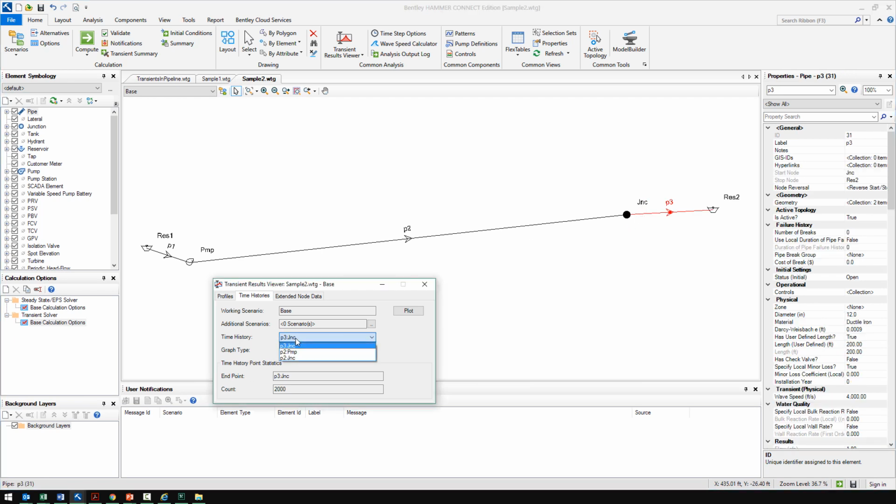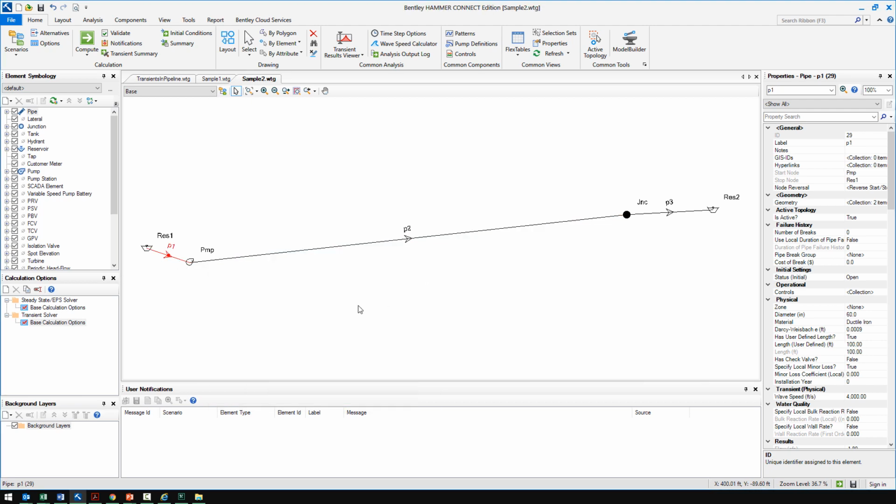And that's more significant, especially for things like pumps. So if we look at P2 colon PMP, we're talking about the discharge side of the pump. Whereas, and I don't have it included as a report point, but if you wanted to look at the suction side of the pump, it would be P1 colon PMP. So just a terminology thing there.